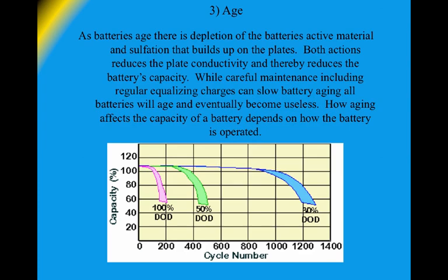In my system design for static applications of photovoltaic systems, I generally plan to not be discharging the battery more than 50%. I truly like to cycle the battery in the top 25% of the battery's capacity. This is going to obviously give me a great deal of extra battery life.